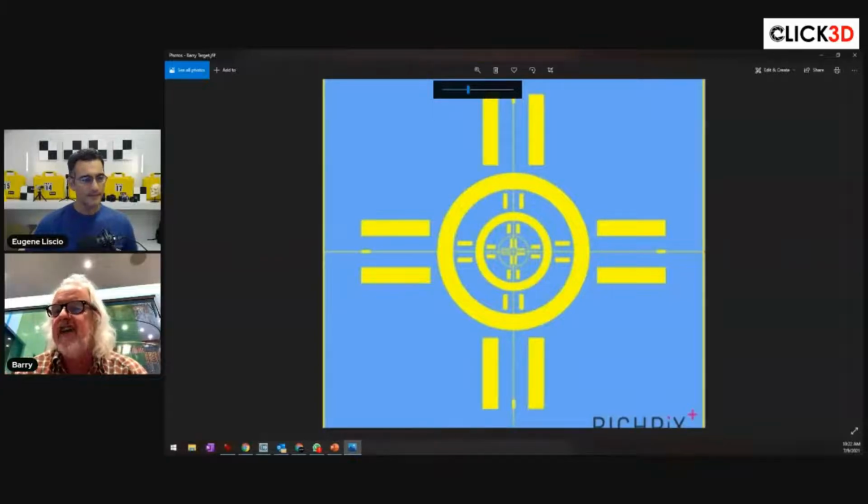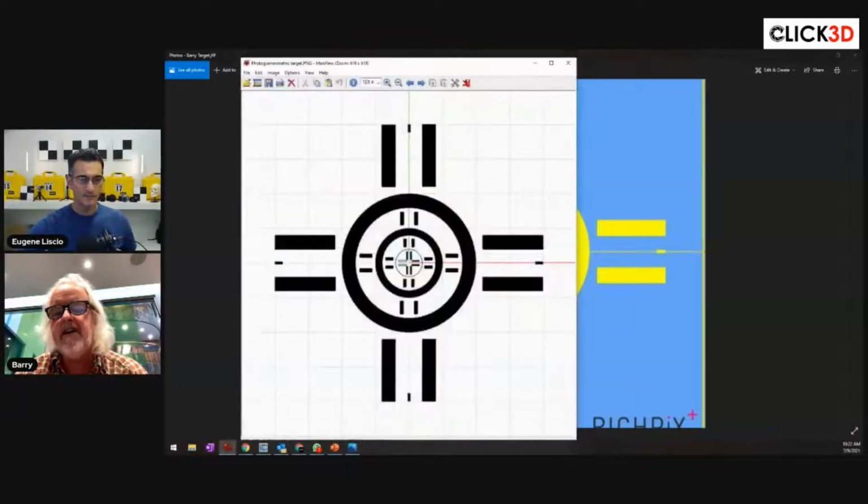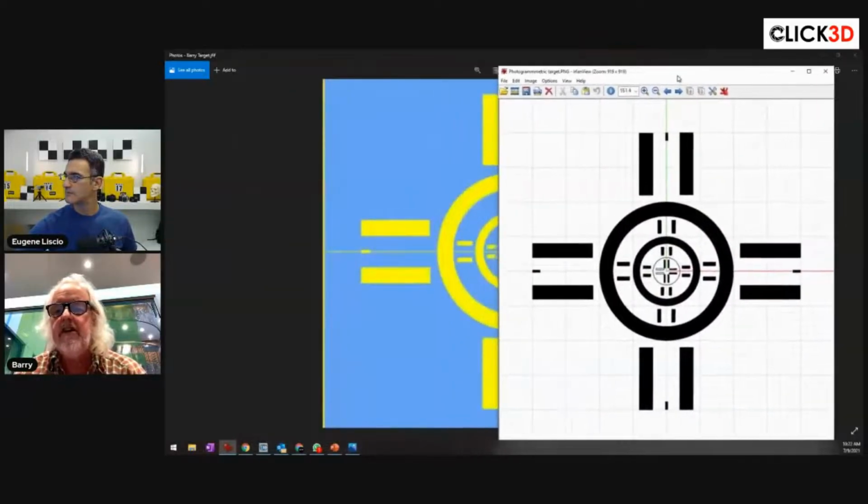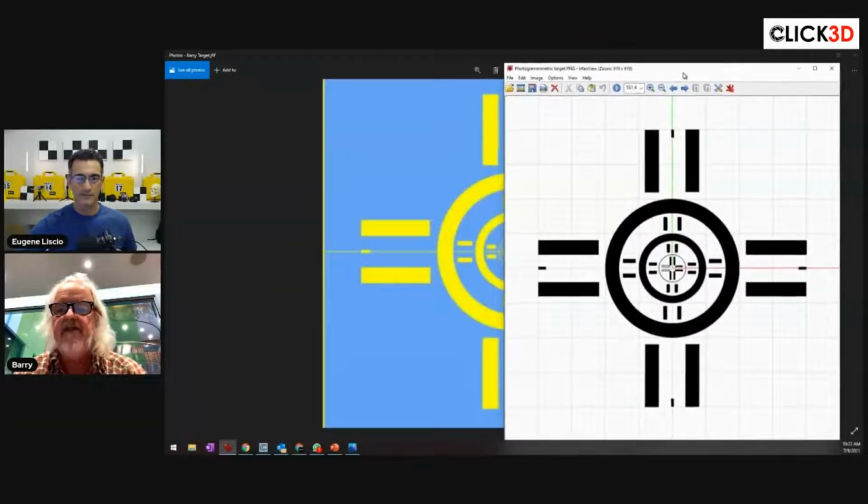Right. The original design of these is in black and white. I changed it to this sky blue and primrose yellow. And the reason for that is just an article I read about color, and the visibility and why emergency vehicles are painted different colors. In England, we have red fire engines. Apparently, that's one of the worst colors you can have because it just disappears in the dark. But blue and yellow is one of the common things that's used on emergency vehicles all across the world. And the reason being is because it's the best combination visible in different light.